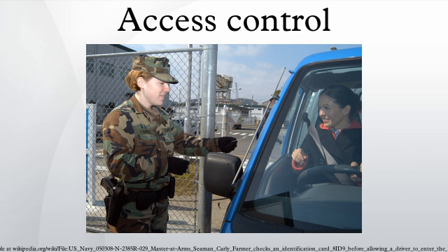3. Serial main controllers and intelligent readers. All door hardware is connected directly to intelligent or semi-intelligent readers. Readers usually do not make access decisions, and forward all requests to the main controller. Only if the connection to the main controller is unavailable, will the readers use their internal database to make access decisions and record events.